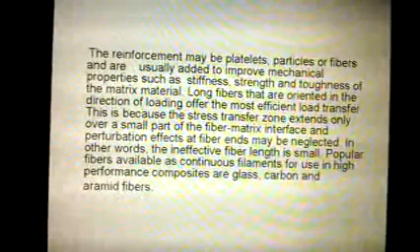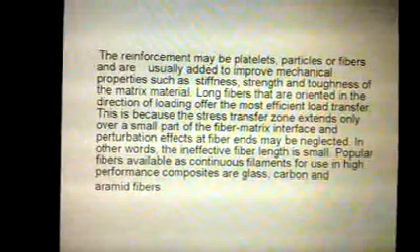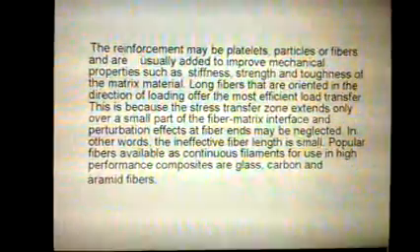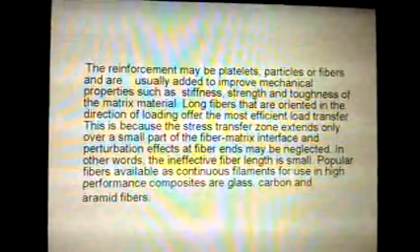The reinforcement may be platelets, particles or fibers, and are usually added to improve mechanical properties such as stiffness, strength, and toughness of the matrix material. Long fibers that are oriented in the direction of loading offer the most efficient load transfer.